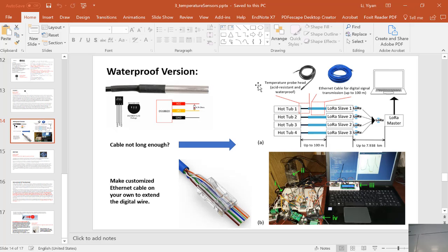So I searched online. One of the solutions to that problem is to use the Ethernet cable. You can see the Ethernet cable is everywhere, right? They're relatively long because the special design of the cable can reduce the capacitance in between the cables. That's why you can send the signal through a long distance at a relatively high speed through that type of cable.